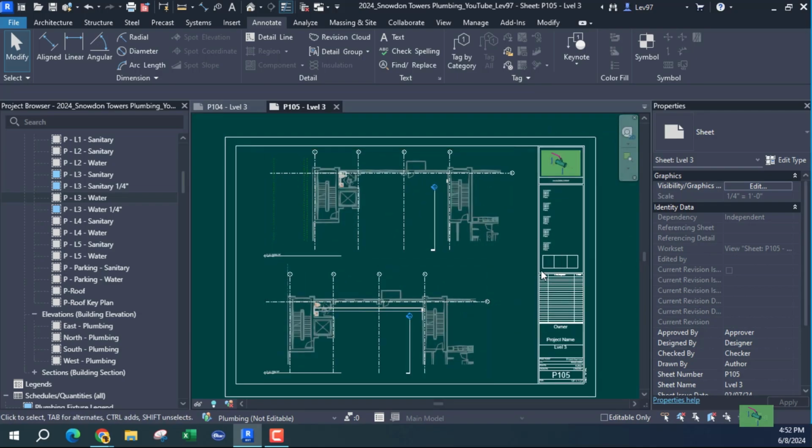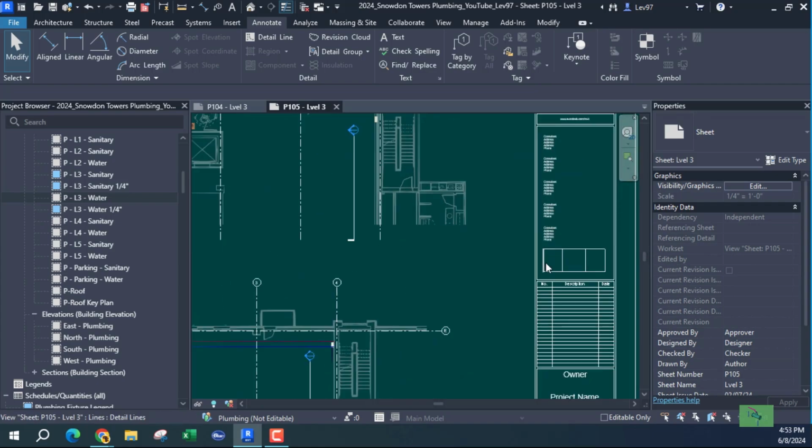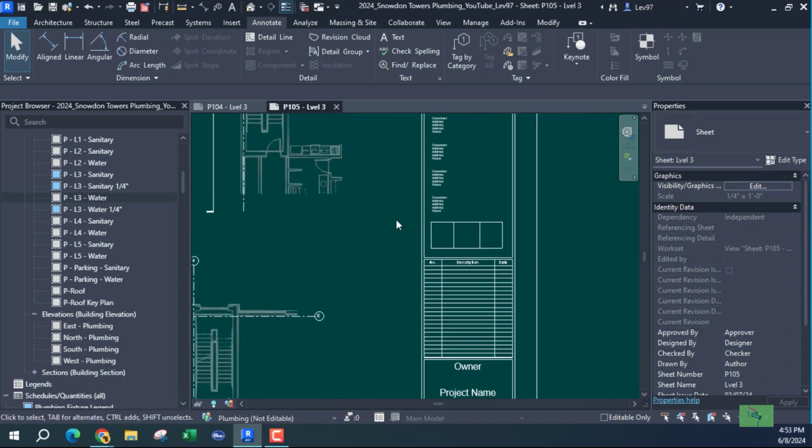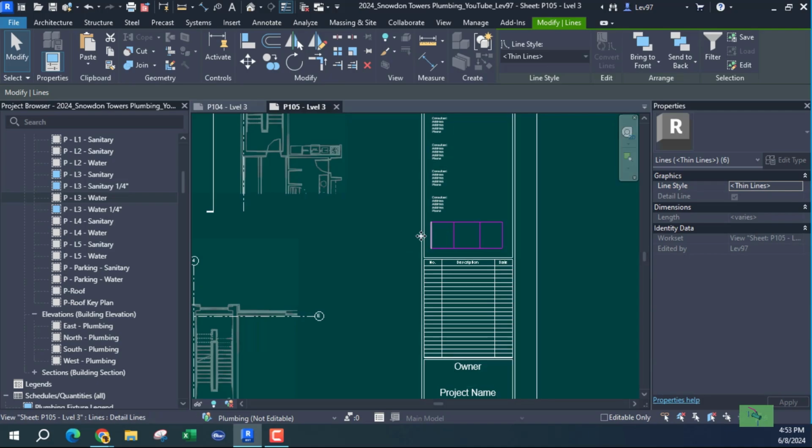So let's do that, and we're going to use a project parameter, and we're going to use what's called a field region, and we're going to use a new family. It's an annotation family. So let's go through that exercise. First, after you've laid out your footprint for your building, copy that to your clipboard.